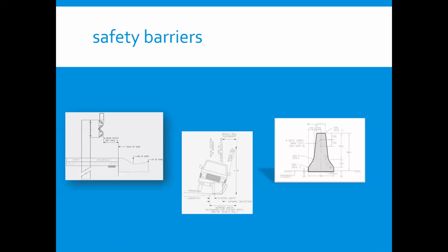The back of the curb and channel should be located at least 3 meters from the face of concrete safety barrier for all curb types. At least 3 meters from guardrail barrier or wire rope safety system for barrier curbs, and between 0 or 1 meter or at least 3 meters from guardrail barriers or wire rope safety barriers for semi-mountable curb.